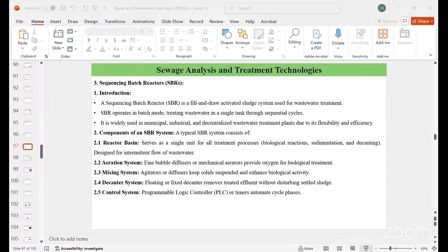So it allows the separation of the solids and the liquids by using the membranes, which helps in eliminating the need for the traditional secondary clarifiers as well. So these basically work in a process where the wastewater enters the reactor, which consists of microorganisms which play a crucial role in breaking down the organic pollutants, similar to activated sludge process. And instead of settling the solids in a clarifier, the mixture is filtered through the membranes, which retain the solids and bacteria, producing a clear, high quality effluent.